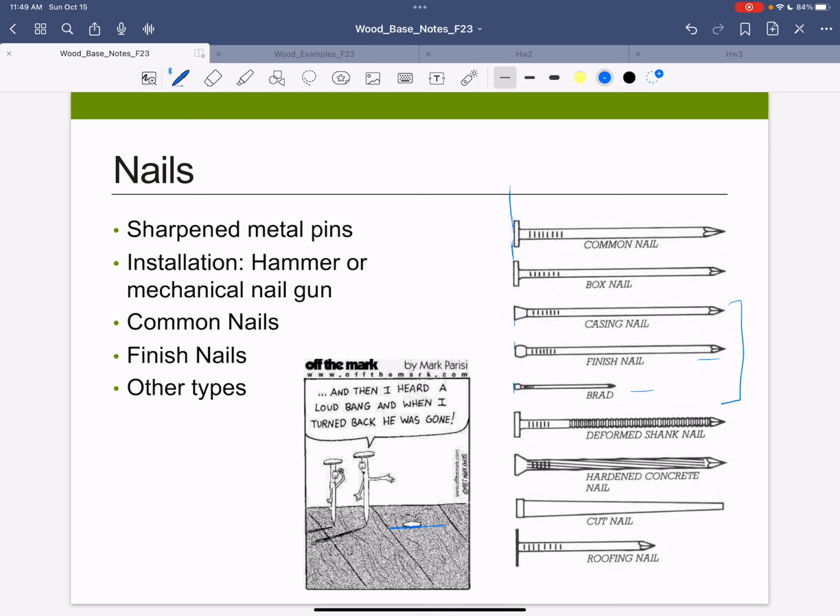The finishing nails are good for putting on my big trim pieces. The brad nail gun is good for putting on pieces that are attached to the trim pieces, or some furniture applications and things like that. Right. So these are the small little ones, and you can go back and make sure they're finished off correctly so that you don't notice them right away. So you'll see this on trim work.